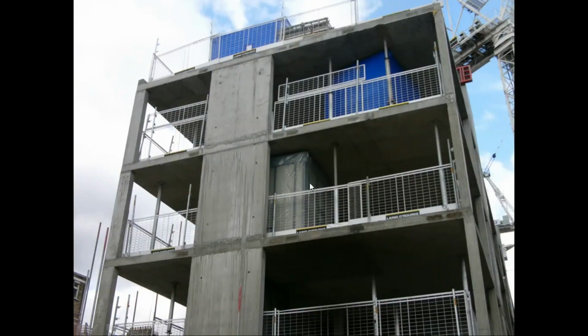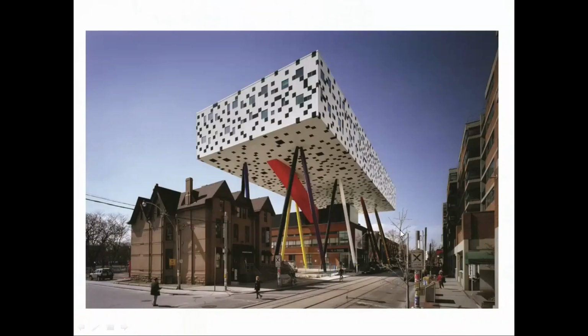So this is not a pinwheel structure, but next time you look at a building site and you think, hold on a minute, here are the columns. They're not exactly square, but they're fairly squarish, and suddenly you come across these big solid concrete blocks. What are they doing? It's not because the load is suddenly heavier at this point. This whole element is bracing the structure from lateral load in either direction. There'll be one in this direction, and there'll be one somewhere else in the other direction.